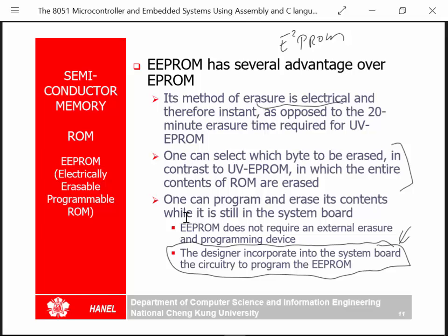That's a huge advantage, because we could put the pins in there to connect it to a programmer on the board itself and reprogram it in the system. So when we're debugging the software, after we've already built the hardware, we don't have to remove the chip.